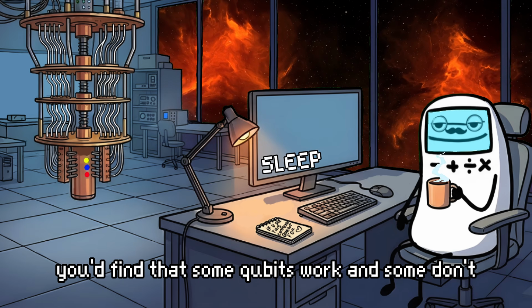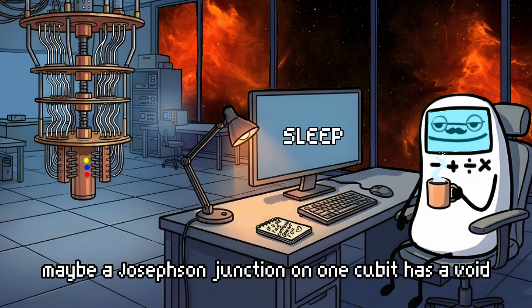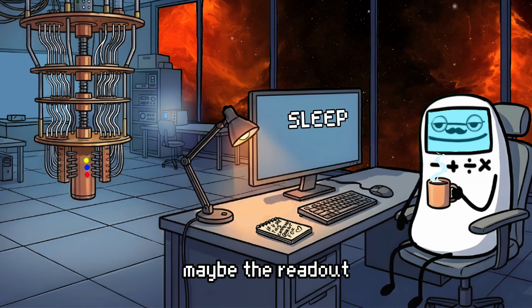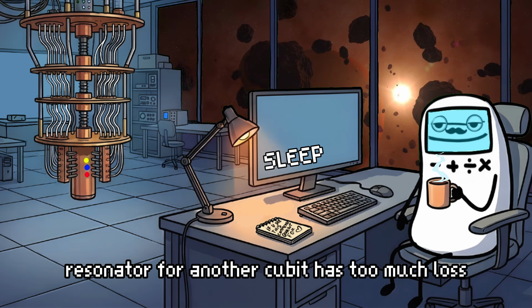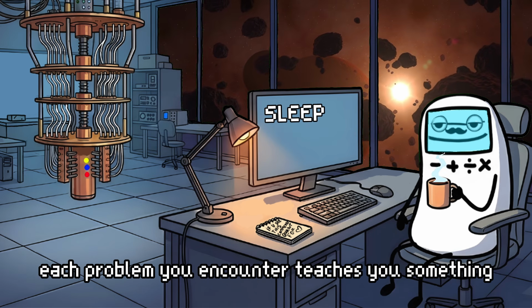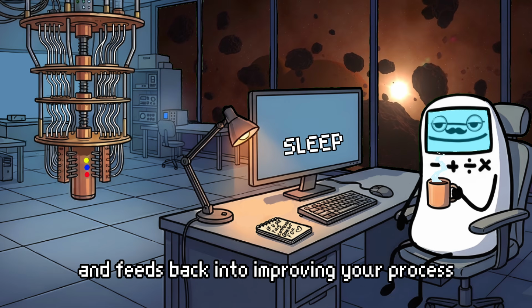You'd find that some qubits work and some don't. Maybe a Josephson junction on one qubit has a void or a short, and that qubit doesn't behave right. Maybe the readout resonator for another qubit has too much loss because of surface contamination you didn't remove in the cleaning steps. Each problem you encounter teaches you something and feeds back into improving your process.